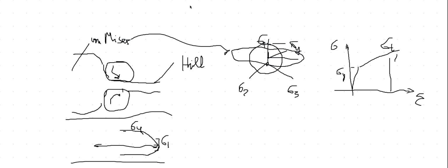But this is simply because in one direction the material was hardened and in the other direction it was not hardened. And this is definitely a much better description, because you take into account what the plastic deformation is in this particular direction. So you have the epsilon plastic, and this happens in the lamination, at the time t for any value of x, and that's precisely what I had in mind.